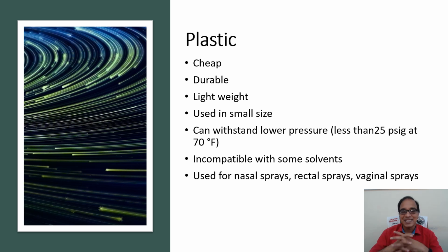Now moving to plastic. Plastic is cheap, durable, lightweight, and it is used in small sizes. It can withstand lower pressure as compared to aluminium, steel, and glass, in the range of less than 25 psig at 70 degrees Fahrenheit.